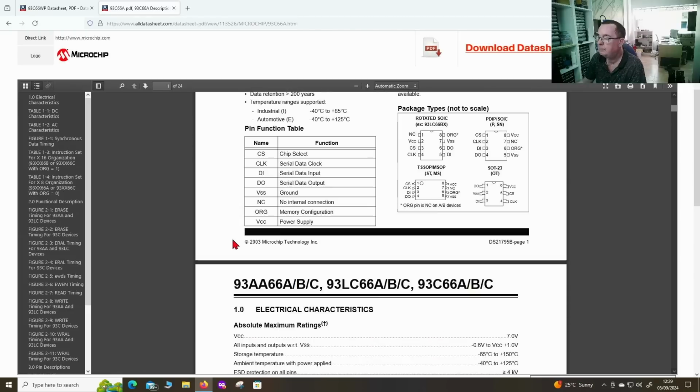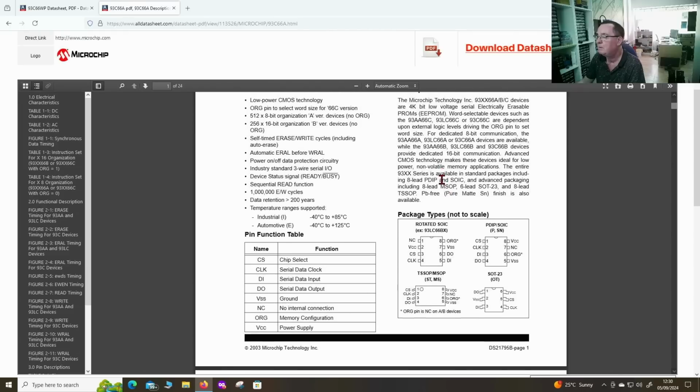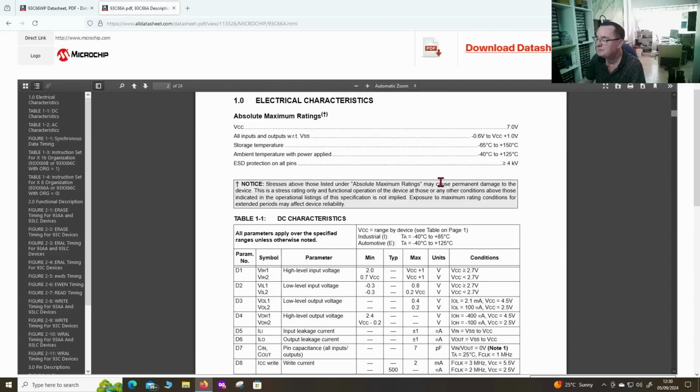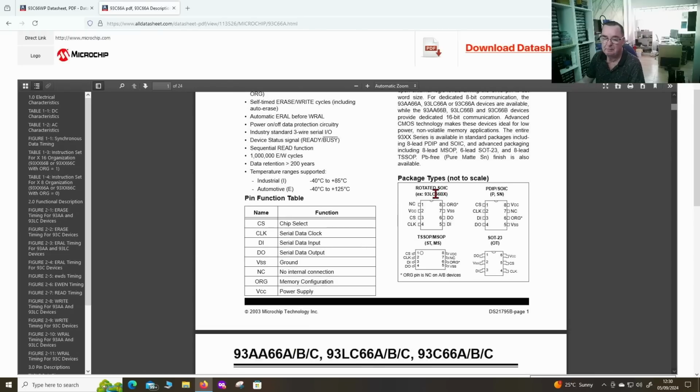Okay. It has a chip select pin, which could be on 3, could be on 1. That's kind of like the pin out you'd probably find on the sort of EEPROMs we're more used to. Okay, so it would be possible, I think, to see whether or not the processor is trying to access the EEPROM. We should see that line. Well, CS doesn't have a line over, so it suggests this is active high, but I wouldn't be surprised if that's just wrong and it's active low. Okay. Who knows, because I don't know this chip. Maybe you know. So that's the EEPROM.